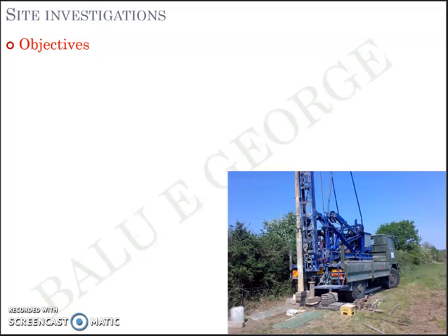As a design engineer inclined in geotechnical engineering, you will have to pay a visit to the site before you arrive at any specific design, the type of foundation, the depth of foundation, the methods of construction, etc. So site investigation is quite important to arrive at an economical and feasible design.